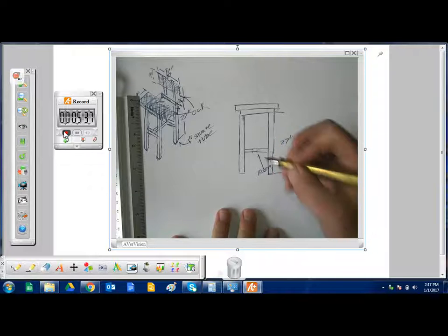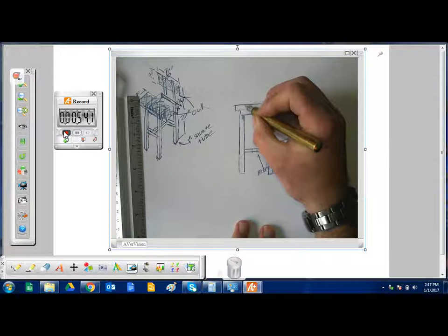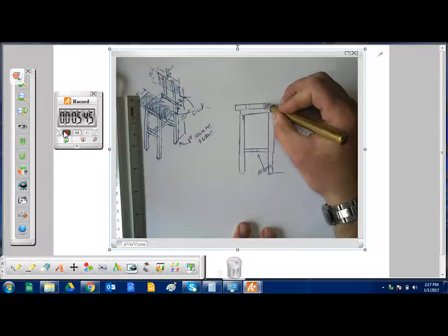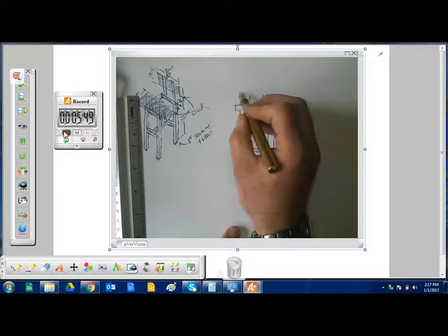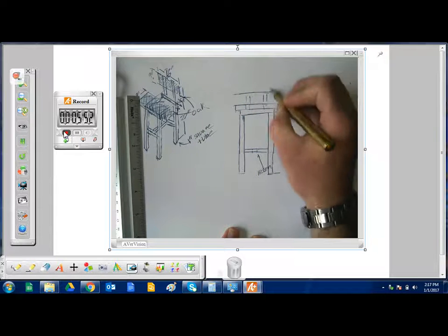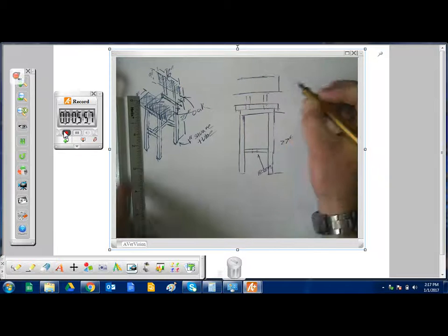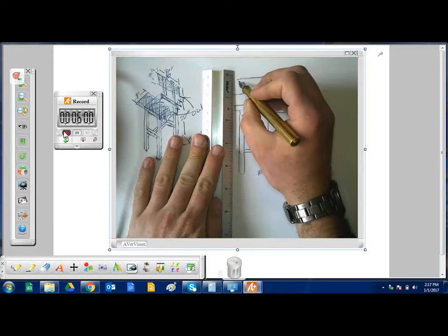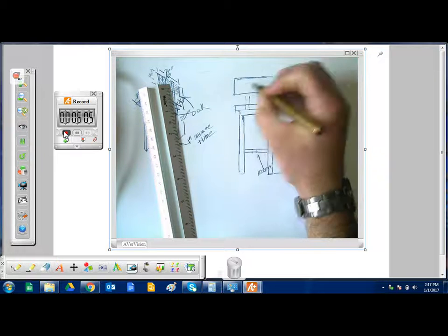If you see a dashed line in this blueprint, you know that what you're actually looking at is a line that you cannot see from that angle, but shows some feature that is hidden. So for instance, I'd have a couple of hidden lines here and here, leading into this thing here, another piece of 1-inch square tube, and then our backrest sits here. There we go.